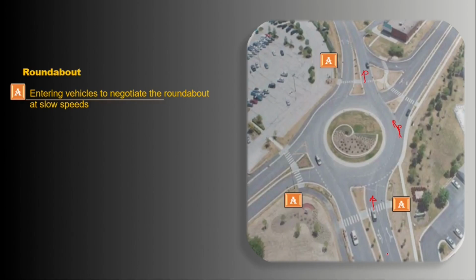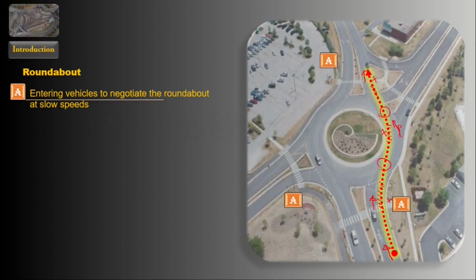As a driver approaches a roundabout, there are three important points that force the driver to follow a path that consists of three consecutive reverse curves with short tangents in between. This is called the fastest path, and we have a lot to do with it in the next section. There we'll discuss how to draw and check the fastest path.